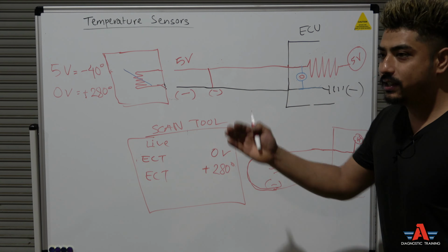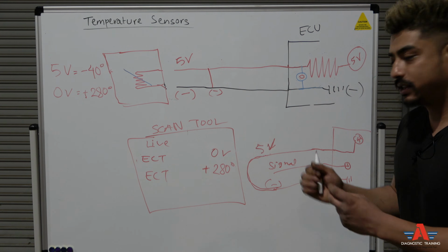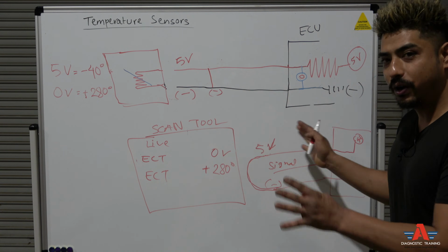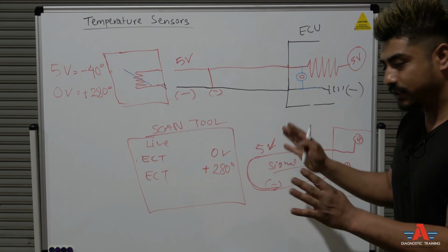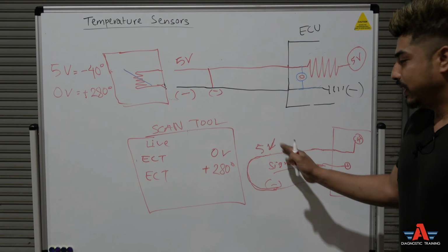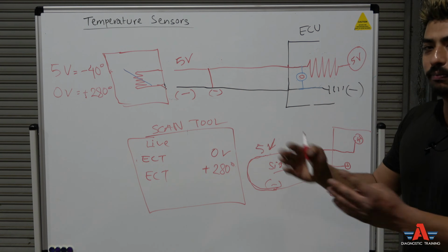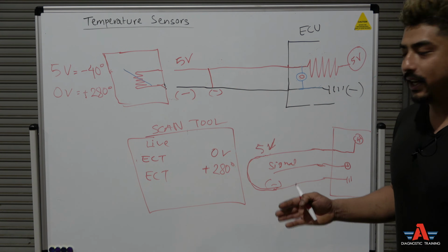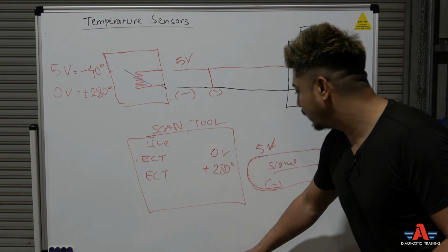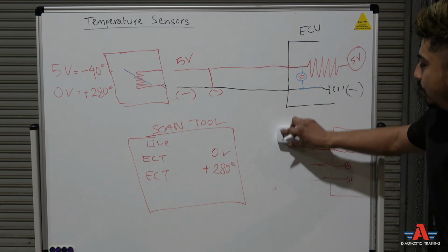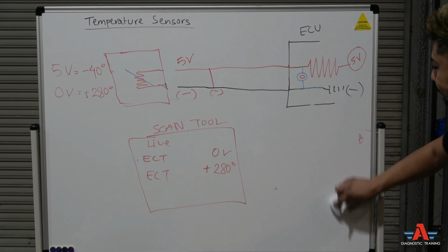And all the sensors are going to have 0 volt because there's a short somewhere in the wiring harness or the circuit on the sensor, whatever. Now you're going to have multiple faults, multiple sensors not operating, okay? That's a different scenario. We can talk about it in a potentiometer class later.